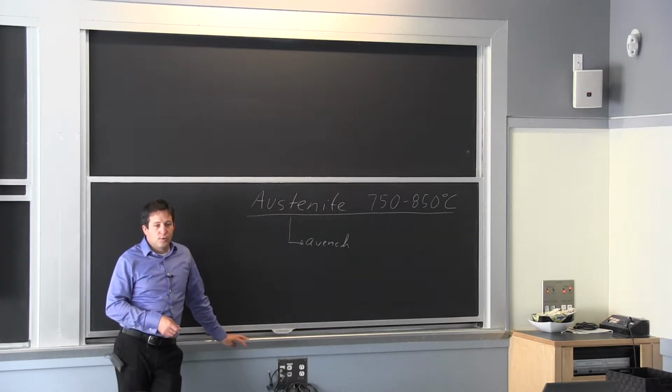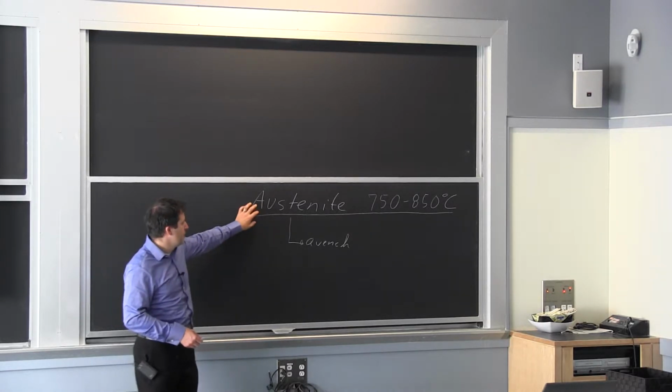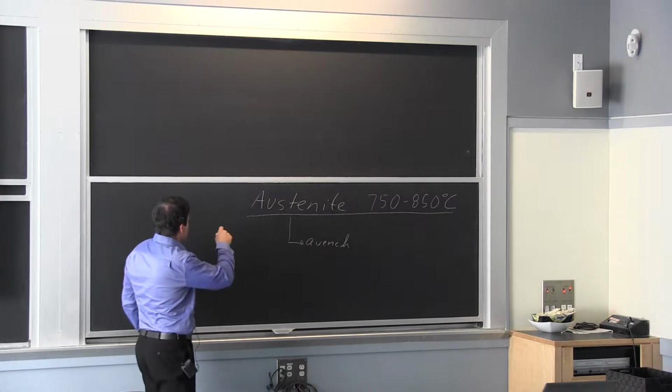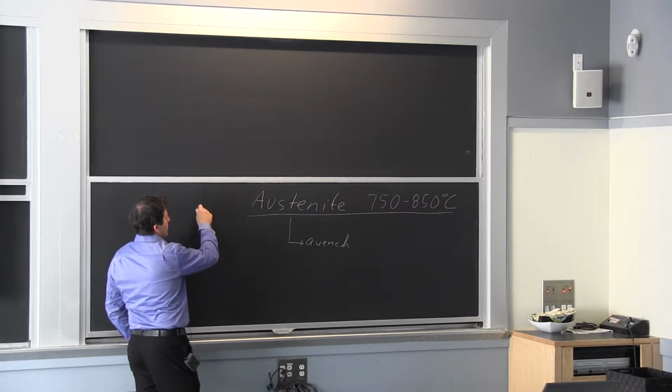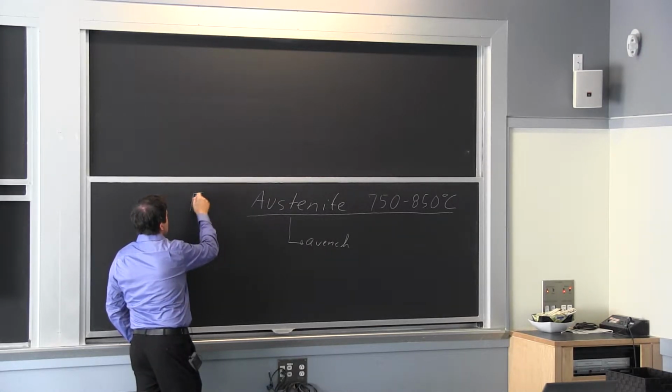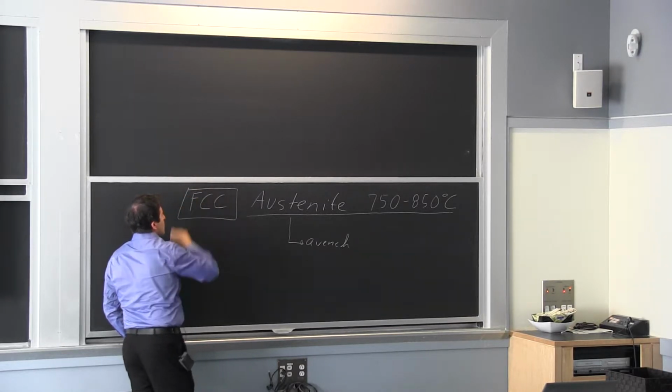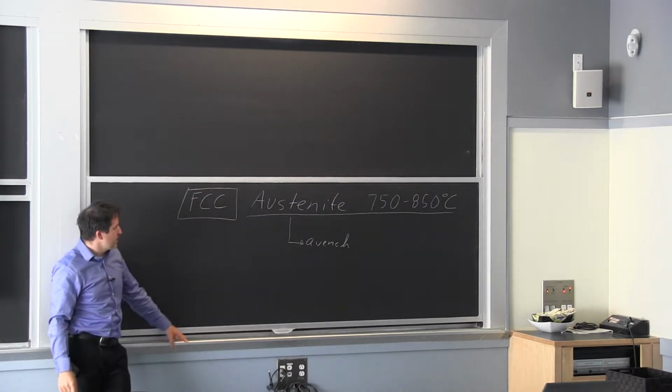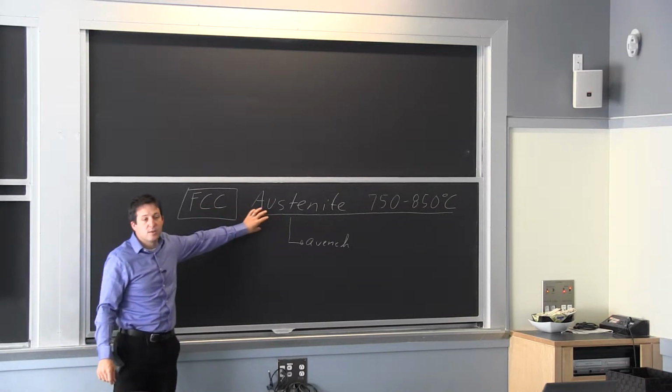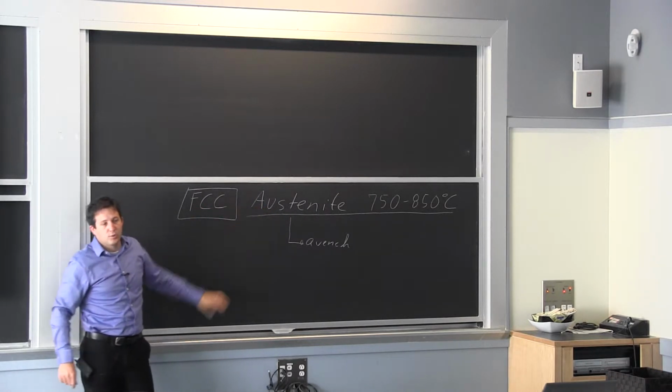and they're used for low temperature application because the austenite, if you remember, is, well, I don't know that I even said that, but it's the face-centered cubic. It's this structure that has more ductility intrinsically. So it's essentially the same structure as aluminum and copper at high temperature.